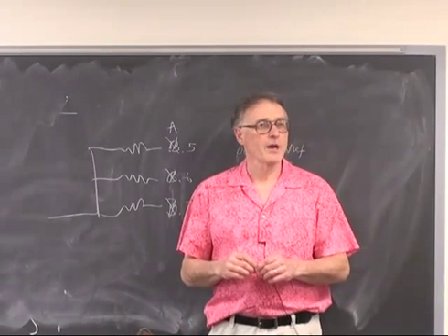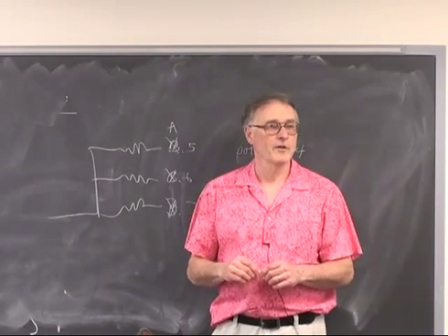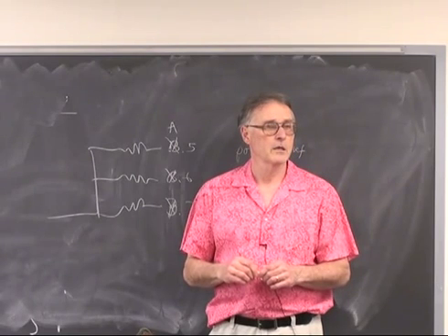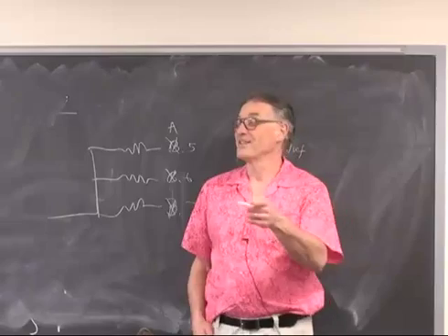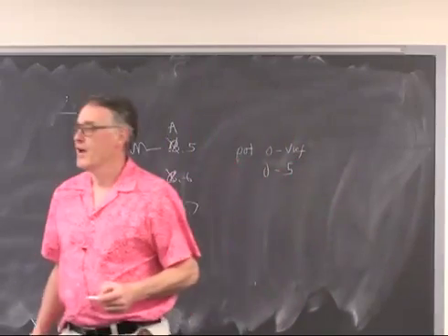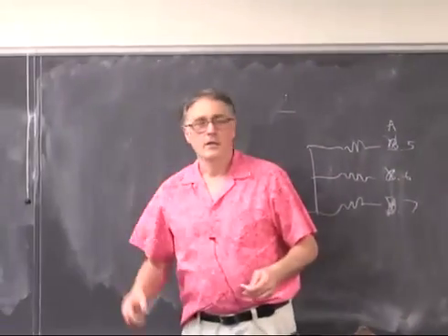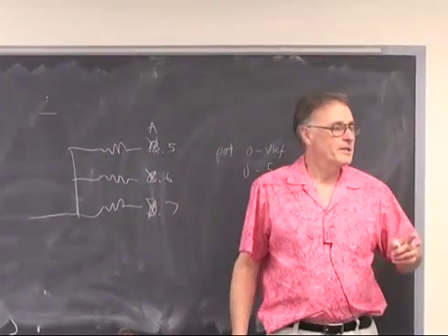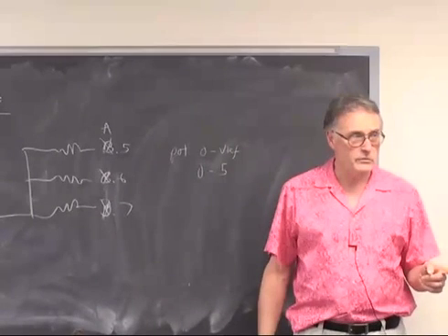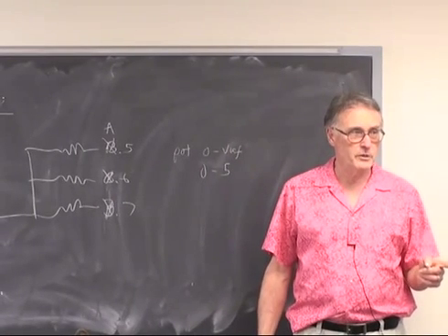Now, how many people are driving the keypad off of port D? That's one, the TA. Okay. Now, that means there's a problem here. You can't debug using the UART because the UART is port D0 and D1.